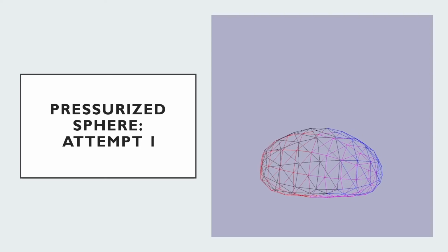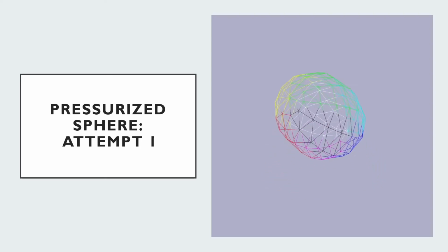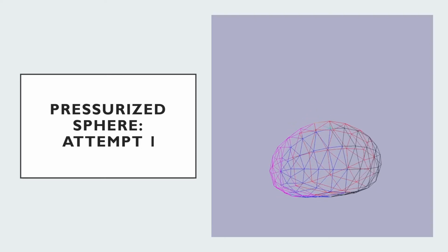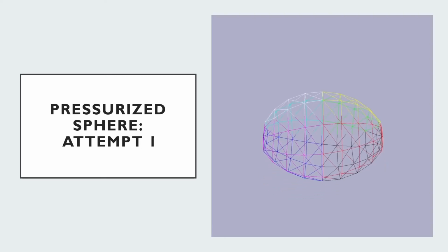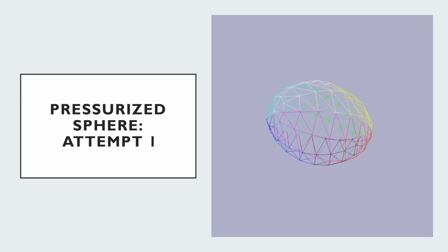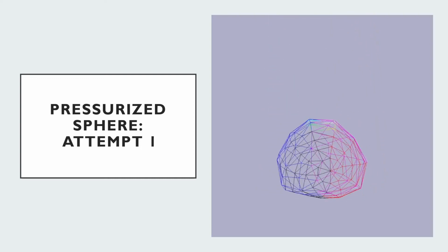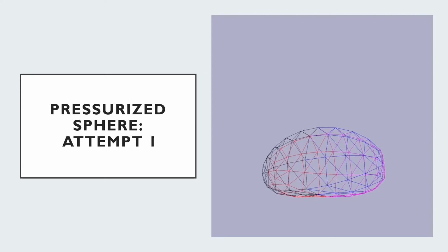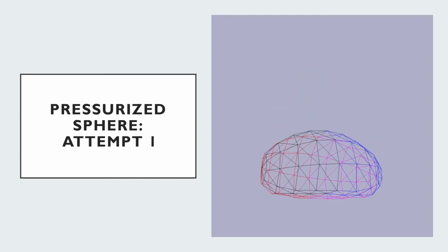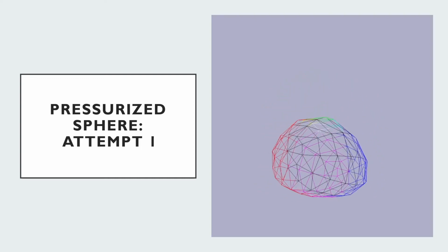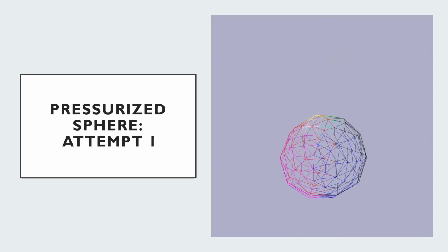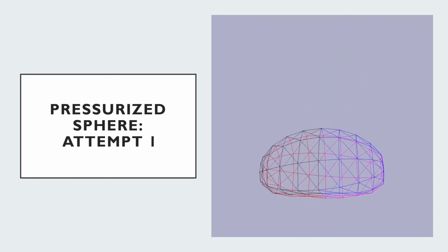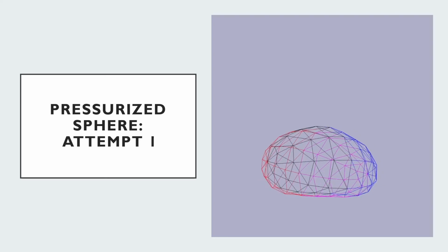And so one important thing I learned when implementing the sphere, in addition to the internal pressure issue, is that your models have to be made with intention for this. So when I initially was just trying to use my calculated sphere model, I ended up with additional points at the poles and along one seam of the sphere. And so that internal pressure actually just caused the sphere to unfurl. So I had to correct for this by finding identical points on the model and making sure that I was using the same points for the springs.